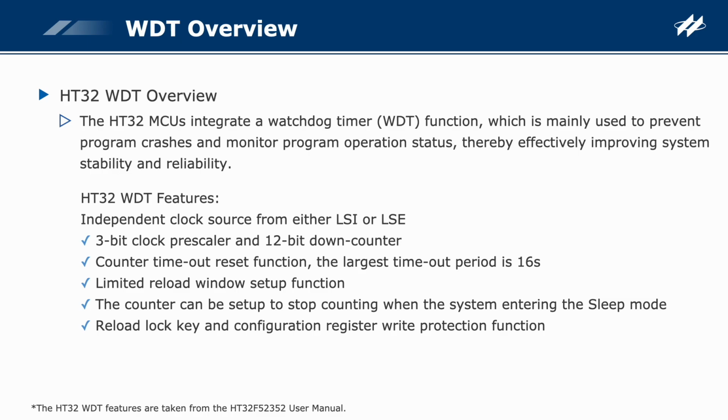Supports a timeout reset function. When the WDT counter reaches the preset value or times out, a reset signal will be generated to reset the system. The largest timeout period is 16 seconds. A limited reload window function is used to customize the WDT reload time within the window time. This prevents the counter from being reloaded improperly or triggering a software deadlock.